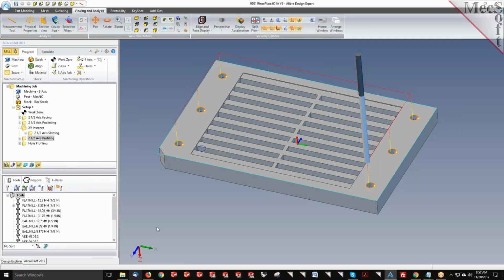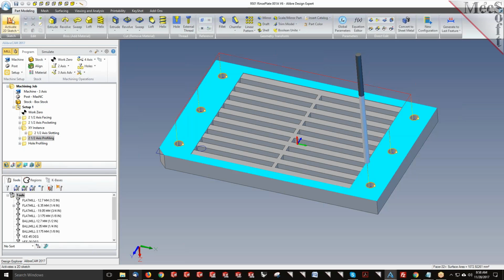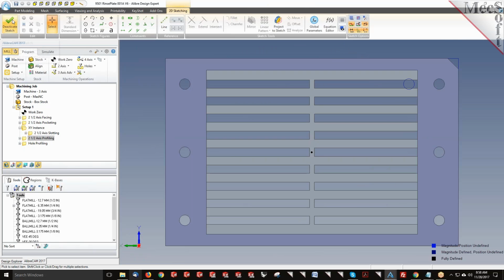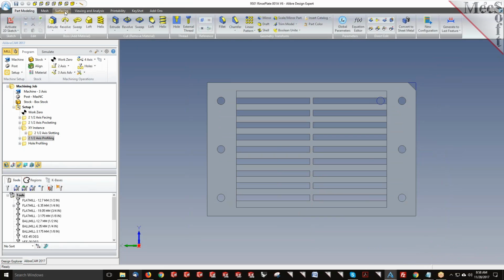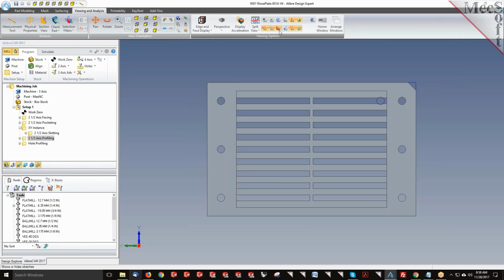Yeah. One of the ways you could do it is you can go ahead and create a new sketch in here in Alibre, and then I could use a rectangle. Maybe I'll just go pick a center, and I'll just throw in a rectangle right there. We can also dimension it. You could say it's going to be 40 by 30 millimeter. I can display the sketch.